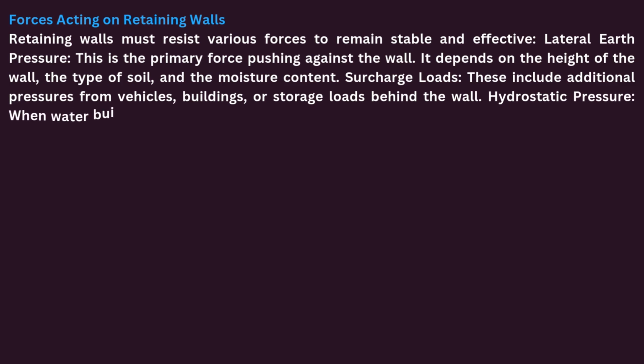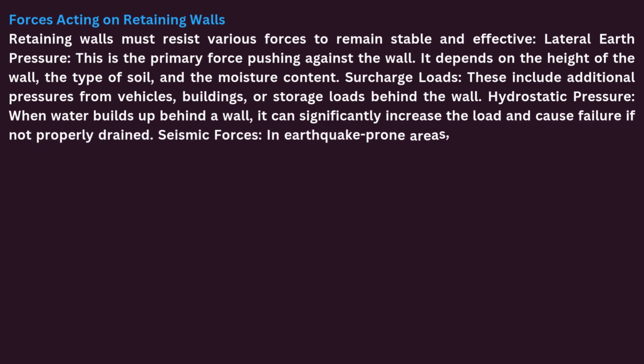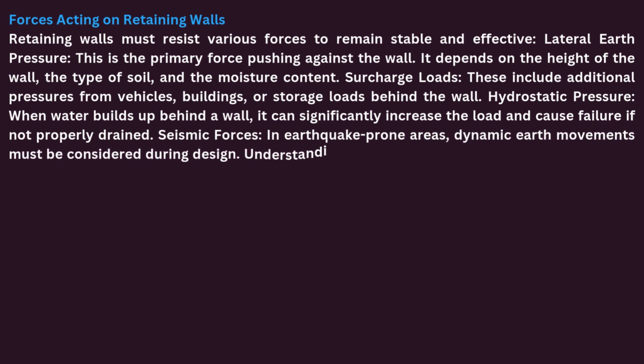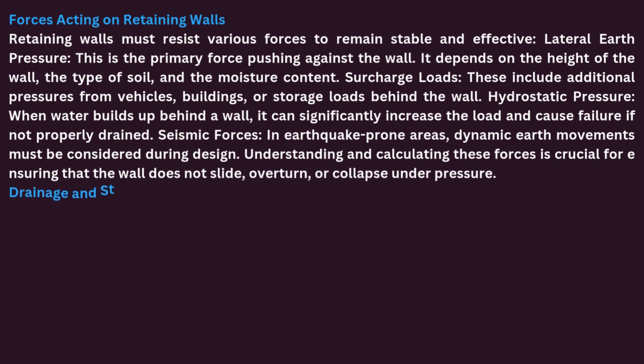Hydrostatic pressure. When water builds up behind a wall, it can significantly increase the load and cause failure if not properly drained. Seismic forces. In earthquake-prone areas, dynamic earth movements must be considered during design. Understanding and calculating these forces is crucial for ensuring that the wall does not slide, overturn, or collapse under pressure.